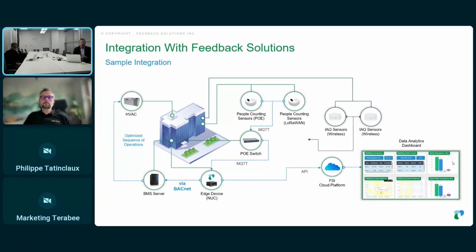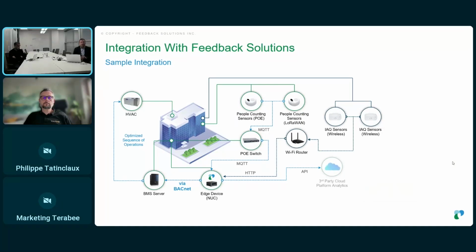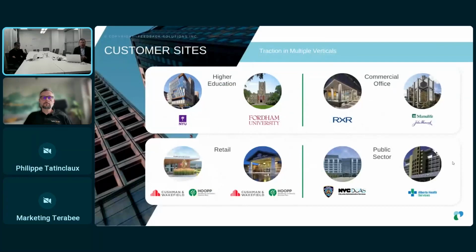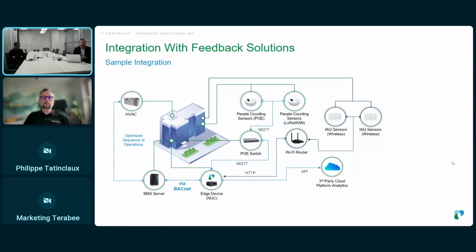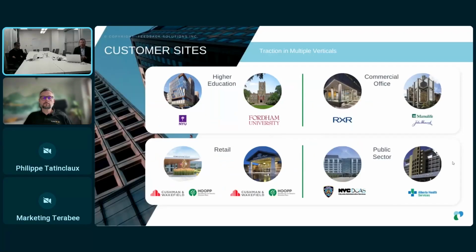At the same time, if there's an indoor air quality monitoring desire, that can also be brought into both a monitoring function and, through the edge device, one edge device per building, we can incorporate that into the sequence of operations and have an automatic ventilation response if there's an alert on the indoor air quality side. At the same time, for the integrators, we can have a third-party integration as well.